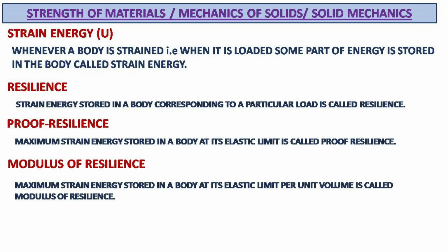Now, modulus of resilience is the maximum strain energy stored in the body at its elastic limit, per unit volume. Or it can be defined as the proof resilience per unit volume. Strain energy stored in a material is calculated by finding the area under load versus deformation curve of the tested material.